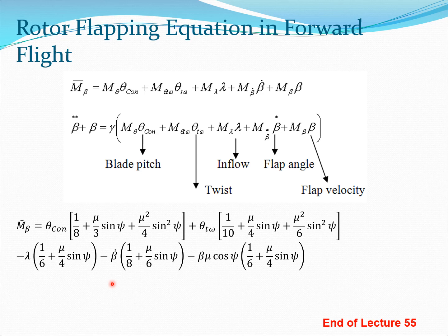So now this equation is worth staring at for a long time because it's going to tell you many things about the kind of forcing you get in a typical helicopter blade and in rotor dynamics in general. This forcing is periodic and motion dependent, and the periodic terms are actually quite substantial, and they are of course dependent on the forward speed. And also the big factor is lambda here, because this lambda is coming from some different model, and lambda in general is also a function of r and psi. Here we have presumed it is not a function of r and we have extracted it out, but that is a simplification we have made.